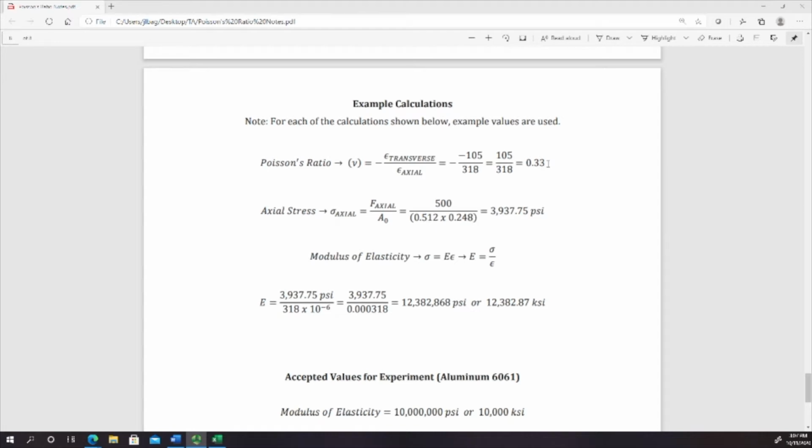In this case also, I want to mention that the values that you see on the strain gauge indicator are in microstrain, which means that the value you see is actually that value times 10 to the minus 6th. So the value you see, if it's 100, 200, 300, 1,000, all of those values are in microstrain, which is times 10 to the minus 6th.